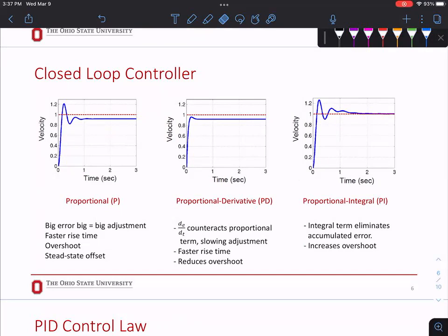It would create overshoot if your P is big, meaning that you're giving more juice, so the system goes whoop, and that whoop might be an overshoot because the system is running faster with bigger power. You might have a steady state offset, some error. So changing P on its own, you might not get rid of your steady state error. To fix that, you add the I. The I will get rid of your remaining error.